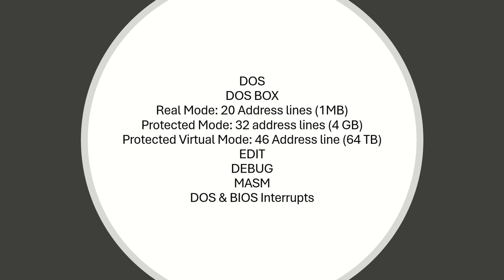The next generation is 8088, because 8086 has 16 physical data lines, but the industry was not ready to accept 16 external data lines. They wanted 16 data lines internally inside the chip, but not externally.